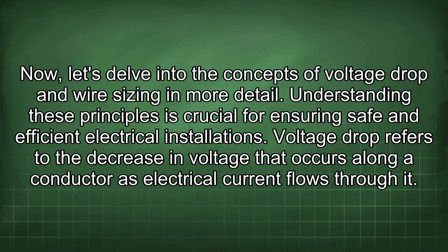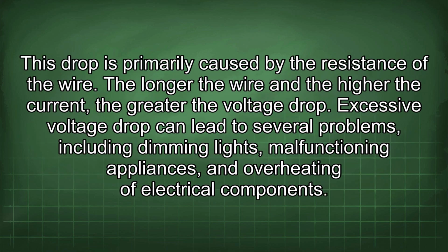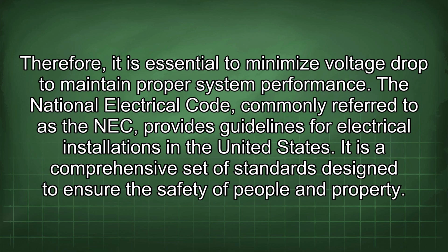Voltage drop refers to the decrease in voltage that occurs along a conductor as electrical current flows through it. This drop is primarily caused by the resistance of the wire. The longer the wire and the higher the current, the greater the voltage drop. Excessive voltage drop can lead to several problems, including dimming lights, malfunctioning appliances, and overheating of electrical components. Therefore, it is essential to minimize voltage drop to maintain proper system performance.